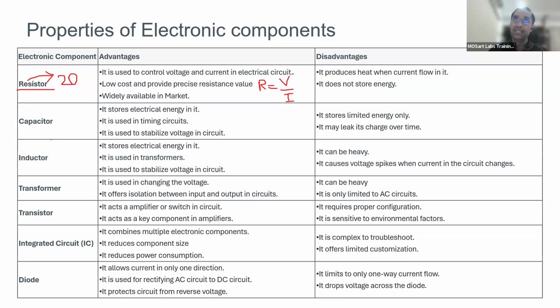Now, there are instantaneous values. For example, if you have a fixed resistor, then this equation V by I, you can even apply as an instantaneous equation and it will still be valid. This means at any point of time, if you have a voltage, a varying signal, some signal that is varying with time, the current that gets generated will also vary exactly in the same phase. V of t and I of t will maintain a fixed ratio always if you have a passive linear resistor.